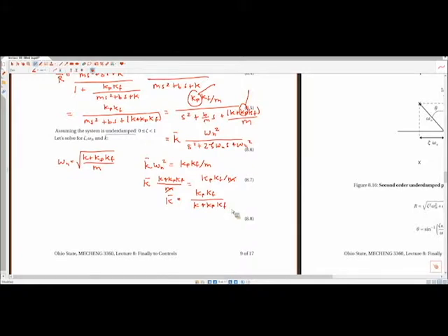Okay, so again, the gain on our system changes with this value kp. So if we were to, say, change kp from a 5 to a 10, that would change this k bar, right? So now you see this is in both the numerator and the denominator, so we'll talk about what that means in terms of performance in a second.